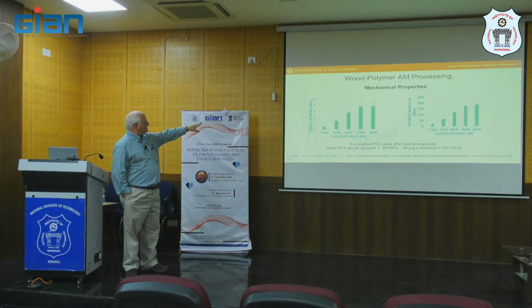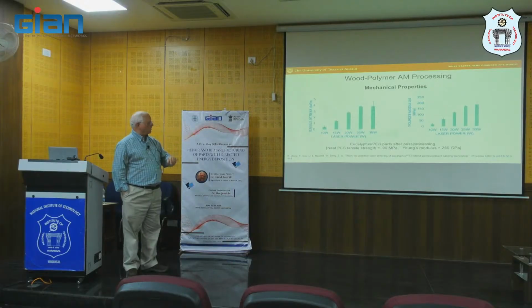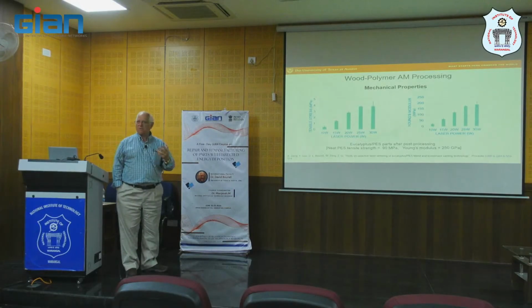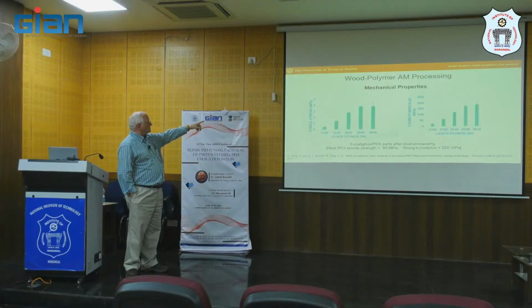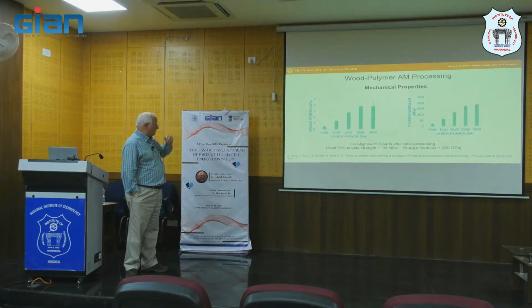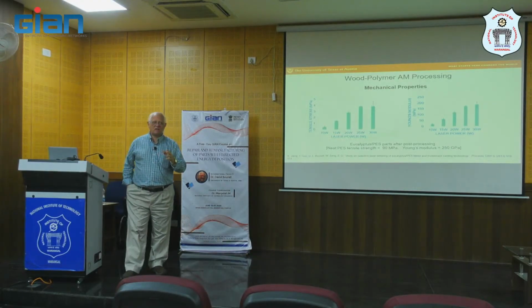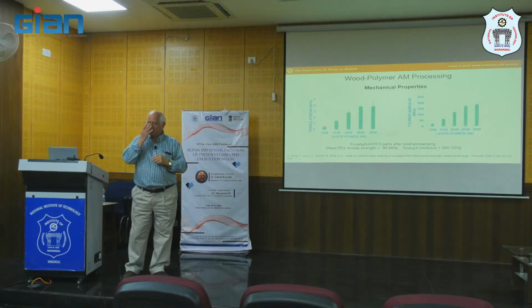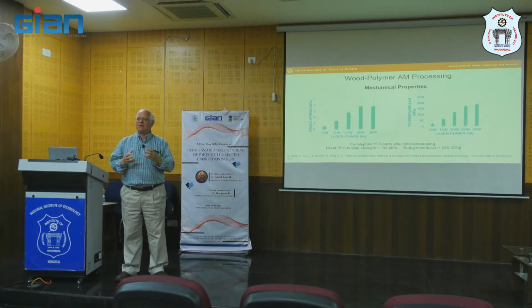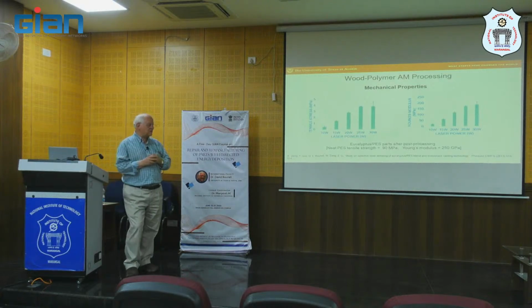So we see over here on this side, depending on what the laser power was for our composite, we got tensile strengths sort of from 1/2 up to about 3.5 megapascal of stress. And what you have to appreciate, just as a rule of thumb, in order to easily handle a material without it falling apart, you typically need about 5 megapascal. So these were very difficult materials to work with, even after processing.